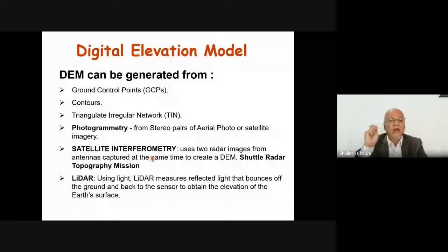And LiDAR can be used on an aerial platform. You can put it on a drone or an aircraft, or even you can mount it on a vehicle and collect the data from it. So you can put a LiDAR antenna like this, look onto the road, and you can just drive on that particular road.